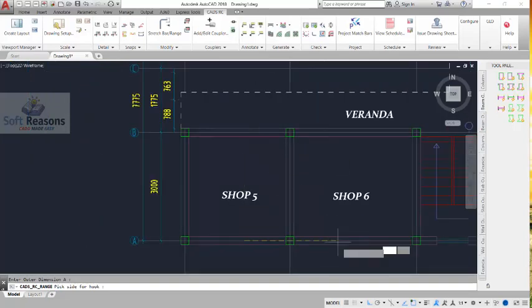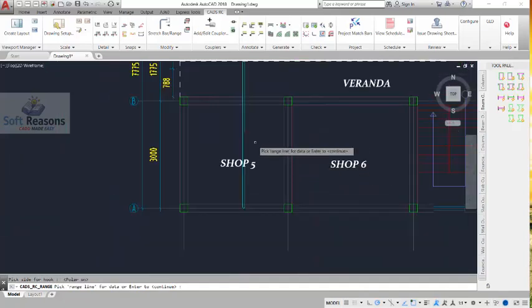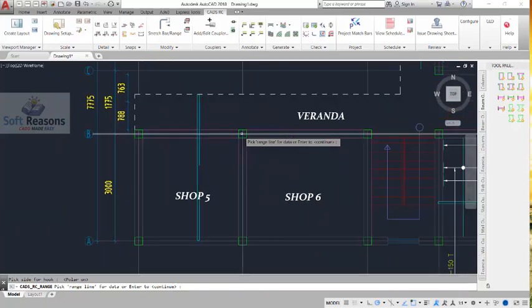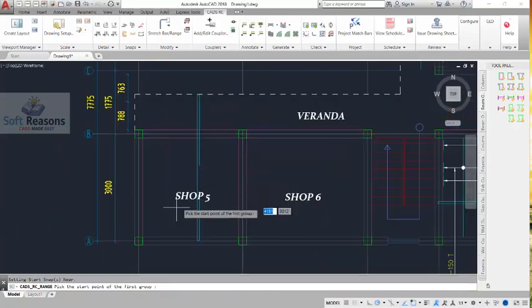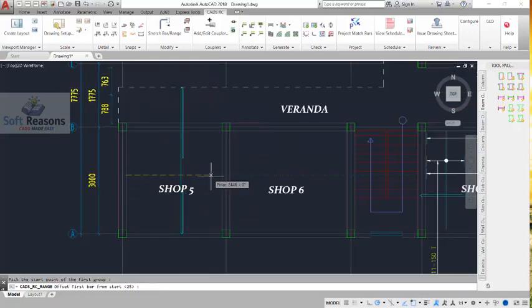Then the hook side, let's get the polar this side, place it. So this is what we're supposed to have. After which you just enter to continue. For the ranging, it's going to start from this point this way. So first 25, and then this point right here, enter, first 25, second 25, and then the spacing is a bottom bar, so we use 100 millimeters. Enter right here.